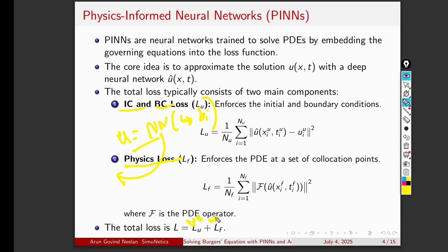This helps if we have some issue in stabilizing the solver. In most of my cases, I use uniform weights because I like to spend more time on architecture than working on this. But in most of the papers, they don't use uniform weights, because I believe the boundary condition should also have a weight similar to the physics or partial differential equation, because the boundary condition decides the solution. In some cases it's very difficult, and the neural network may struggle to satisfy the initial and boundary conditions. At that time, we are likely to give more weightage to the initial and boundary conditions.